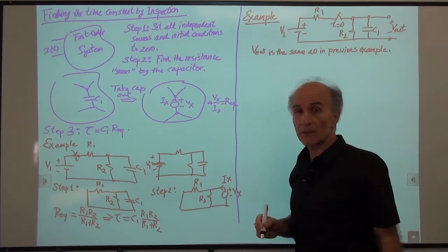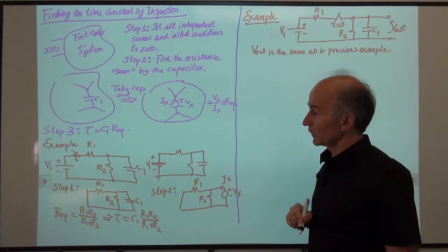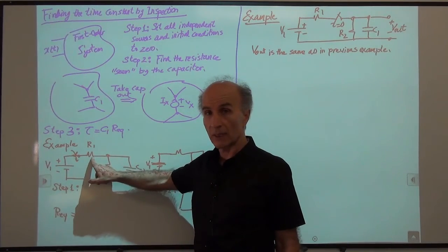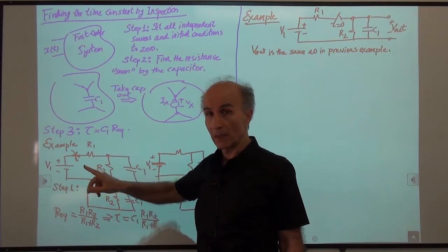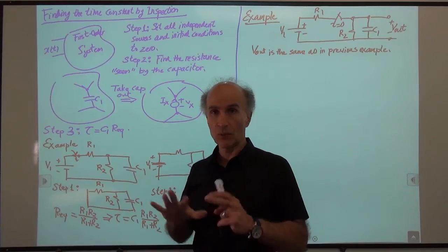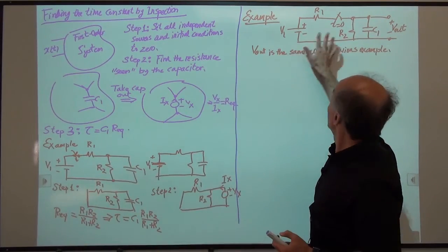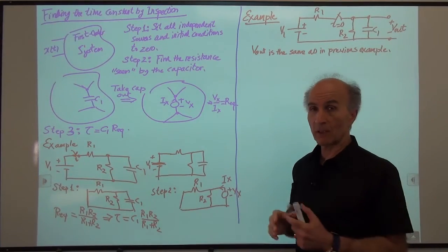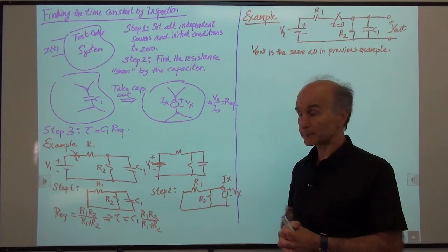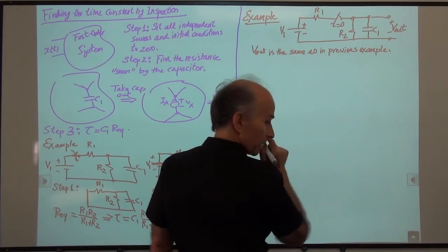Okay, just a little side note, not a big deal, but it's interesting that these two have the same role. In general, anytime we have two devices in series, right, exactly in series, then we can always swap them and the circuit will not feel anything. The circuit will not change at all. That's what we did. These two are in series, I swapped them. This and this have exactly the same behavior as far as all of the currents and the voltages are concerned. Okay, let's see what our timing is like.